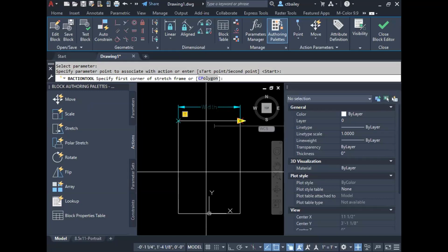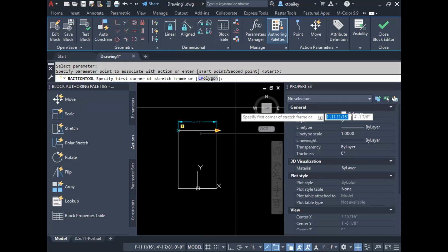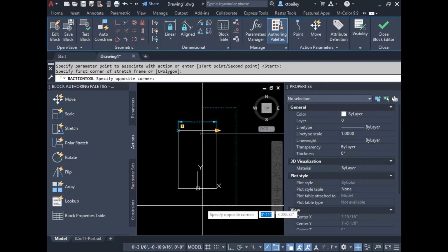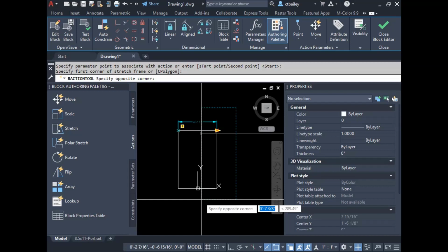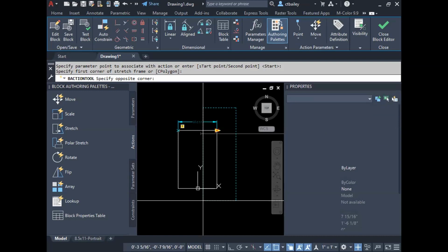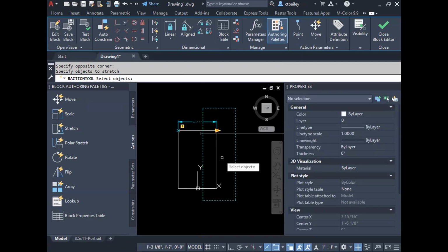So along with this idea of a crossing selection, I'm going to click right here. I'm going to make this little box. And I'm crossing the horizontal members and I'm entirely encasing the vertical member. Does it matter from which side you come at to do it? No. Wait, hold the question, you will see the answer to the question. And fine, so now I've made this little crossing selection and I wanted to hold this line here. So I cut through this line and that line. Last step, select the objects. I'm going to pick the polyline. The whole thing lights up, cool, and hit enter.